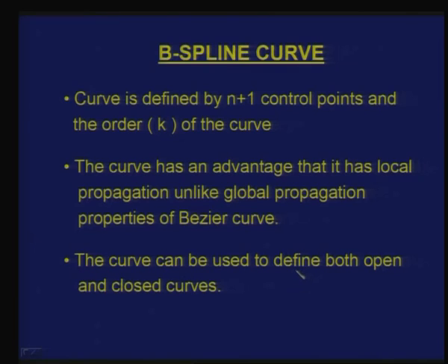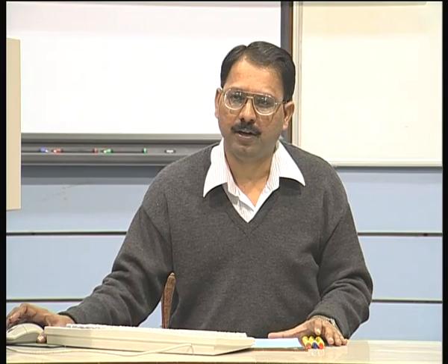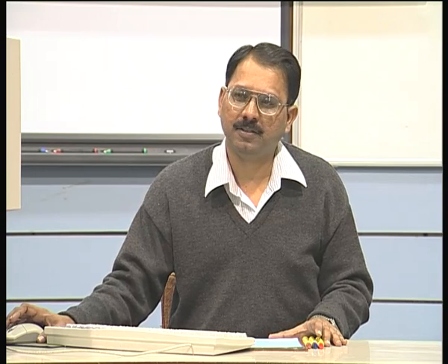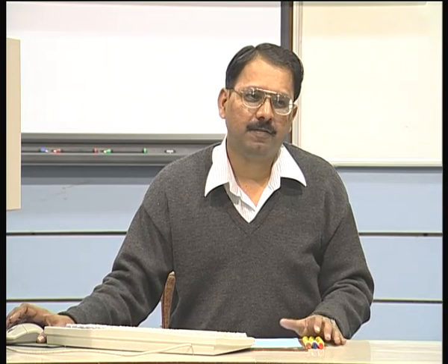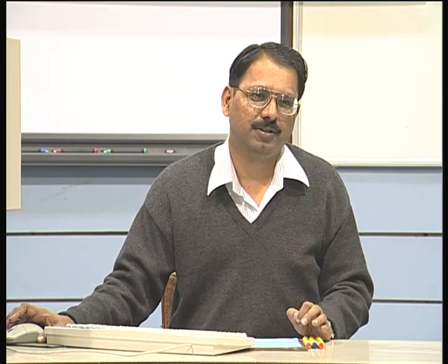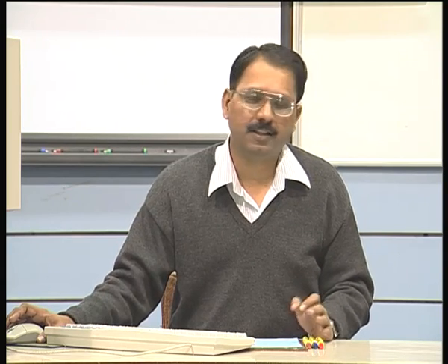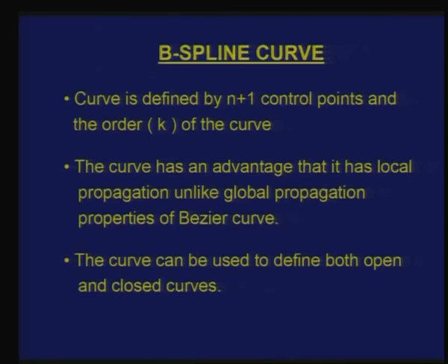Now, another advantage of this curve, which is shown here, is that it has local propagation. When we discussed Bezier curves, we saw that if I am using n plus 1 control points, changing any control point will change the entire shape of the curve, because every point on the curve is defined by all the control points. This is called global propagation of the curve.